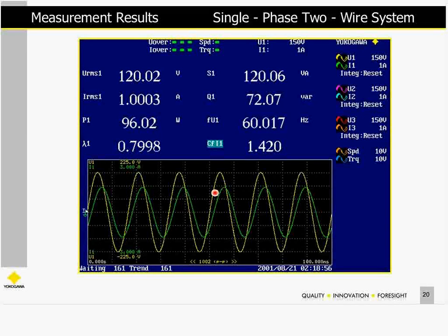It also has a function to do with the distortion of the waveform. If you had high peaks, crest factor could be a lot different. So, on a sine wave, the peak to the RMS is basically the square root of 2, and that's about what we have here. So this is a voltage waveform. The green is the current waveform, and they were both sine waves from the source that we used.